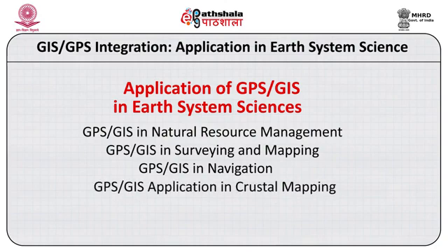Use of GPS GIS application in crustal mapping. Geodetic mapping and other control surveys can be carried out effectively by using high-grade GPS equipment. After 1990, the GPS techniques reached a level where millimeter level accuracy became achievable globally. In geophysics, GPS measurements have been used to monitor and map the crustal displacements for the last 3 or 4 decades.